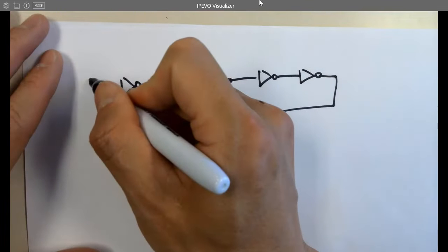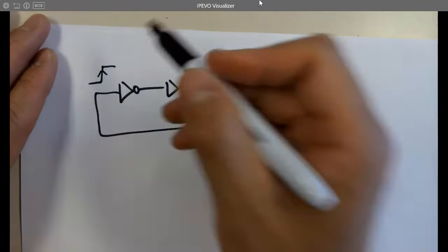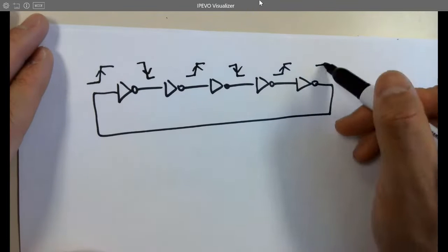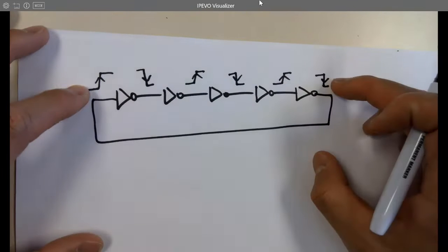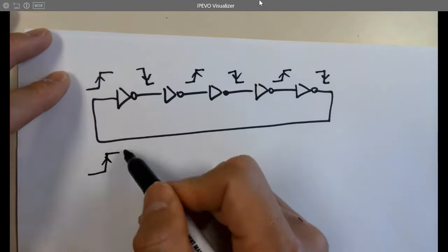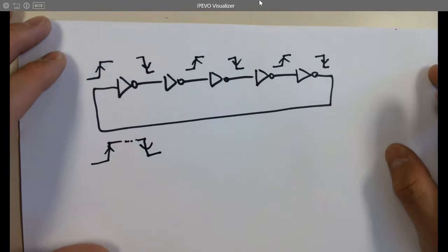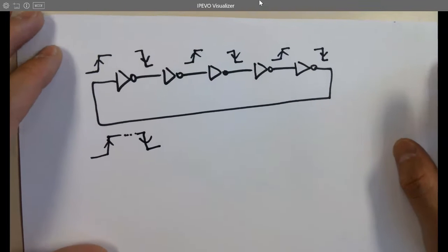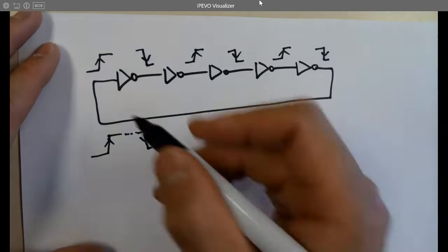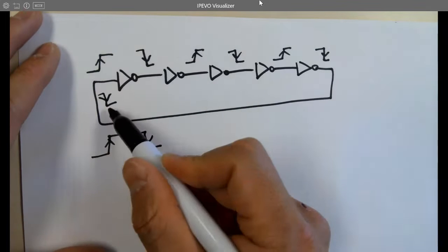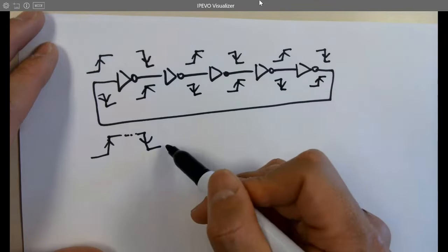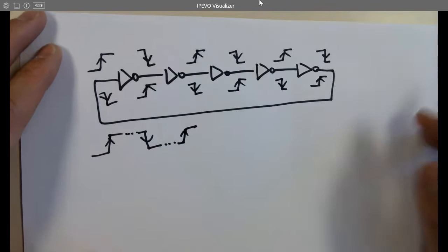So for example, there's a rising edge at some moment here, right? That's going to do this. So it becomes different, but why does it oscillate? Because every single gate will introduce a little time delay. So whenever this one has a rising edge, it takes that delay and then does the falling edge. So it can oscillate. The frequency can be calculated. I'm going to show how to calculate it, but you understand why it oscillates, right? It takes some time for the falling edge. Then this one becomes a falling edge here, and then it's going to do that, and show a rising edge again after some moment. So it's going to keep doing that.